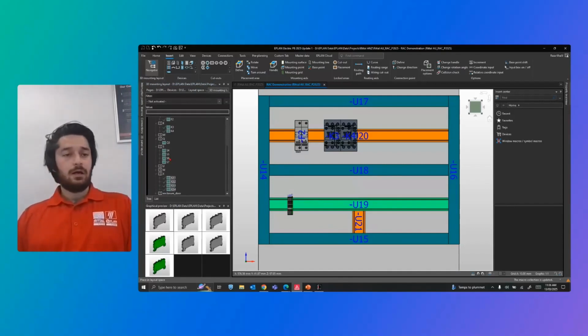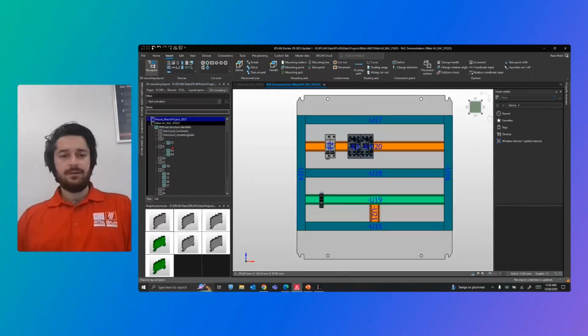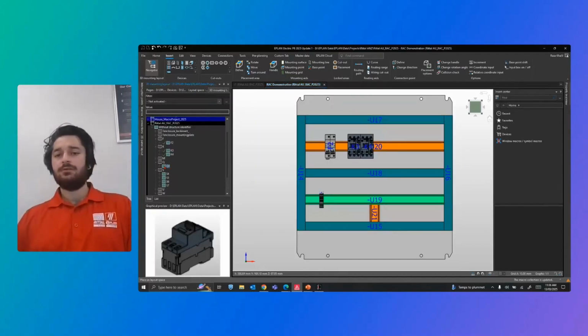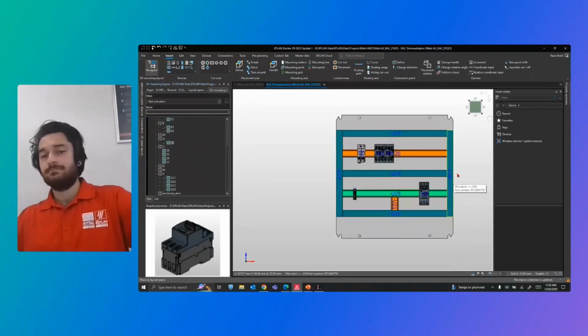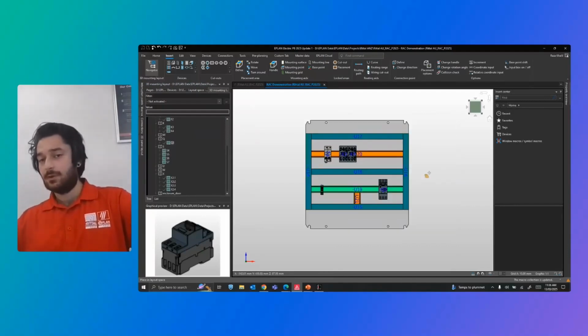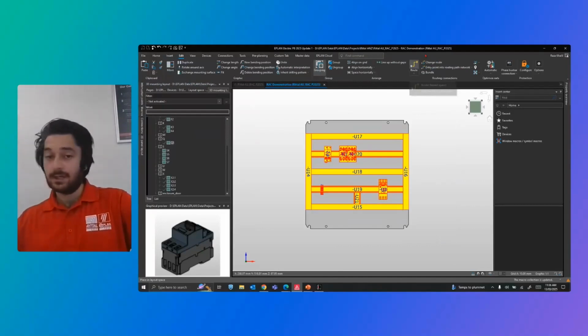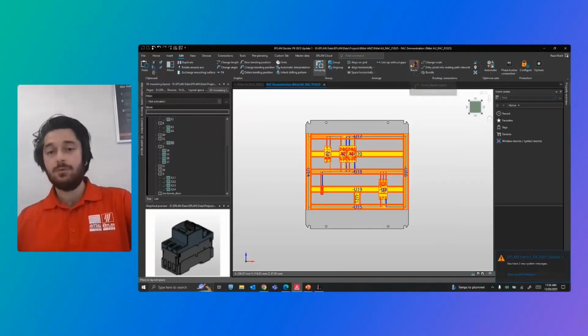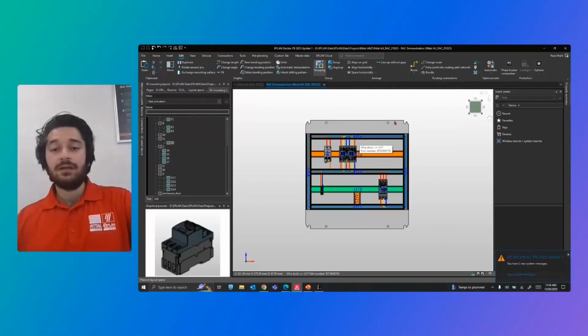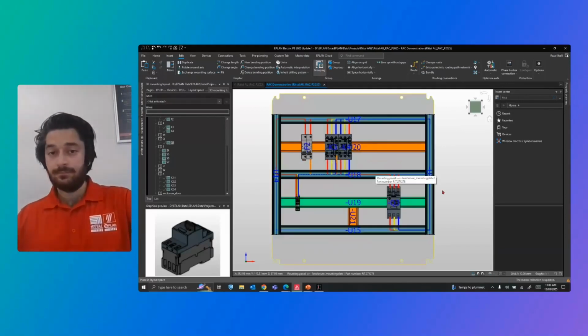Okay. Let's see what else is left. Q3. Let's add Q3 as well. That's fine. And once you're done with this, all you've got to do is just box select, edit, one click. And now what you will see is everything got routed automatically.